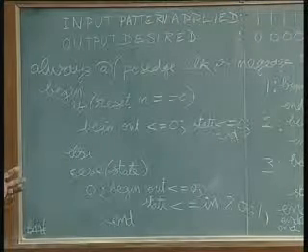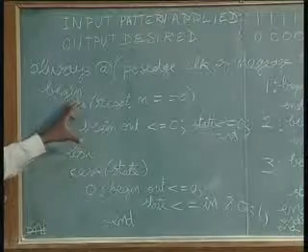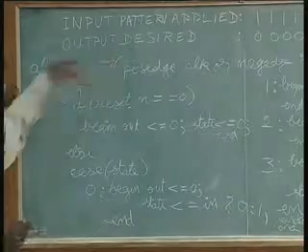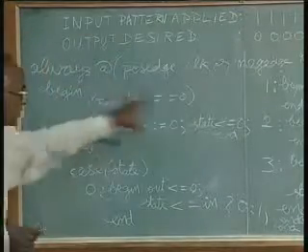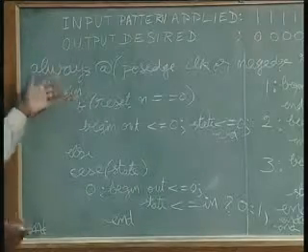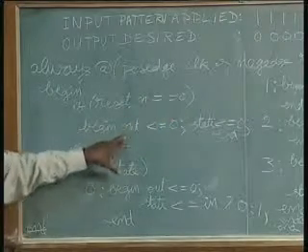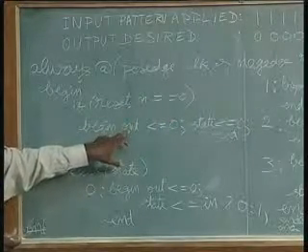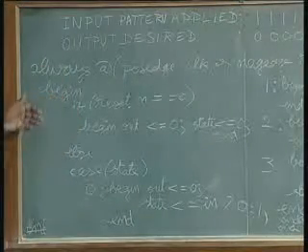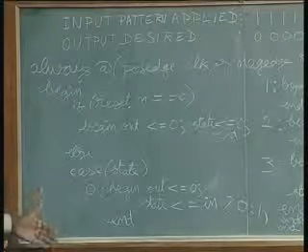When you switch on the system, there will be a pulse created and that will reset. And so long as it is asserted, that long it will keep on rolling, no matter how many pulses have lapsed. It will keep on doing this and get back. If there are 100 clock pulses, naturally 100 times it will revolve around and do only this. The role is only to make the state 0. That's all it will do. And beyond this, after the reset is removed, only then it can come to this portion.